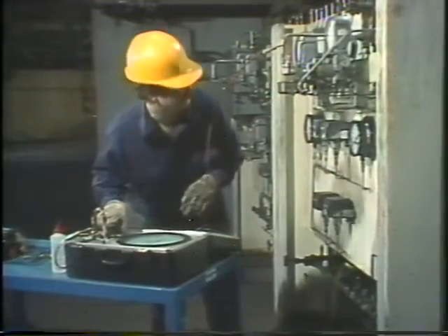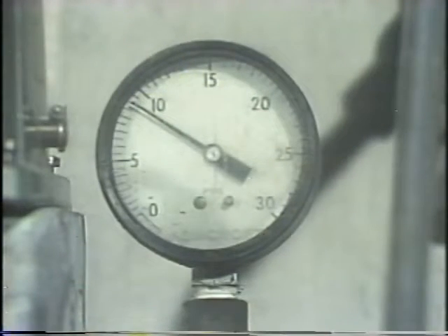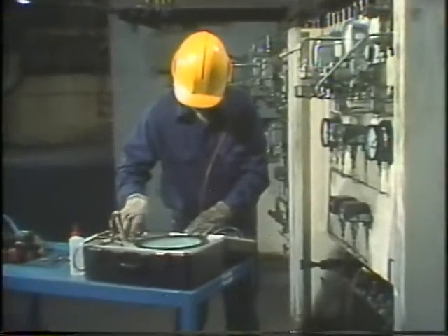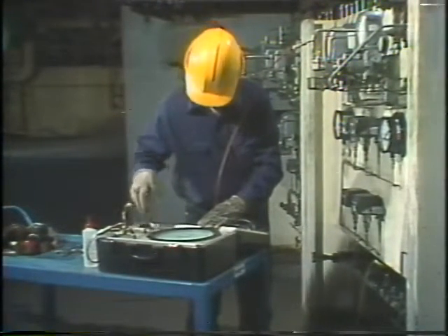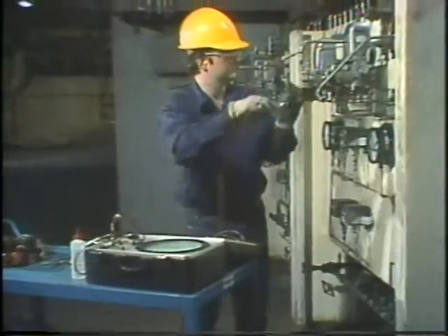There. Yeah, look at that. It's nowhere near 15 psi. That's the output it should be producing right now. That'll require more than a calibration adjustment. I'll go ahead and disconnect my calibrator from the transmitter. I'm going to have to take this transmitter back to the shop. There's definitely something wrong in here.